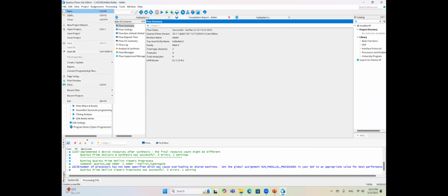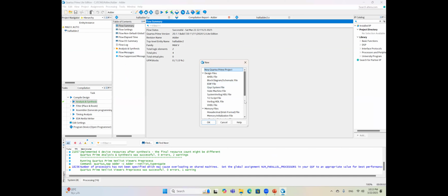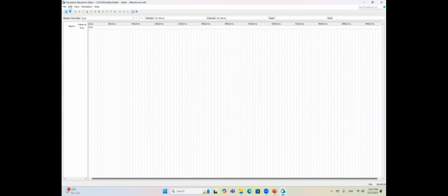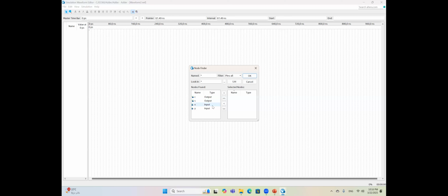We'll say File, New. We'll go down to University Program VWF. It will open the simulator. Edit, Insert, Node or Bus, Node Finder, sorry, List. Let us put them in the right order from the beginning.